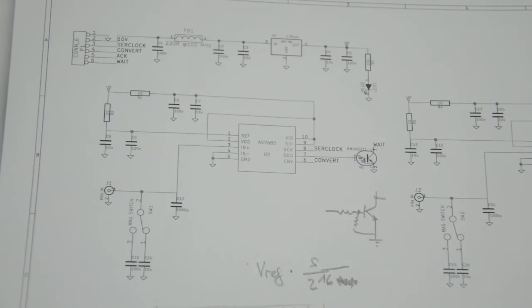But for this spectrum analyzer, it's really not that relevant, because in the end, the way you typically use this is you calibrate your spectrum analyzer, especially if you're testing filters. Then in the end, you will just have a notion of how much your filtered output is attenuated relative to if there was no filter. And it really doesn't matter what kind of reference you have here, as long as it is stable.